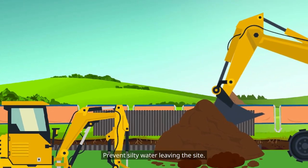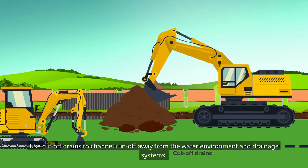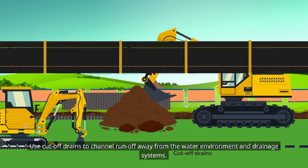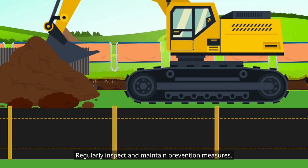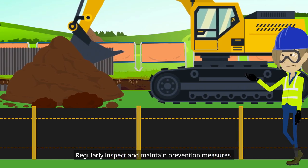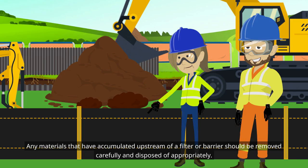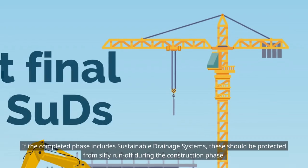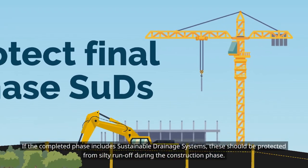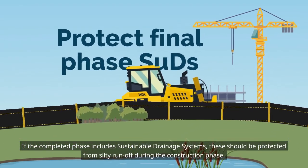Prevent silty water leaving the site. Use cut-off drains to channel runoff away from the water environment and drainage systems. Use secondary measures, such as silt fences, to support the effectiveness of cut-off drains. Regularly inspect and maintain prevention measures. Any materials that have accumulated upstream of a filter or barrier should be removed carefully and disposed of appropriately. If the completed phase includes sustainable drainage systems, these should be protected from silty runoff during the construction phase.